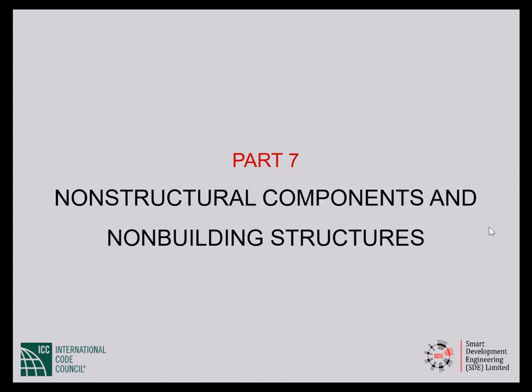In calculating the seismic deflections, remember interstory drift is deflection at level X minus deflection at level X minus 1. In calculating those, if you keep the gravity in place, that would be fine. The gravity that you should keep in place should be, I think BNBC tells you, dead plus 1/2 of the live load.